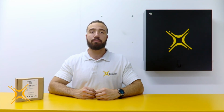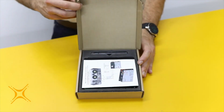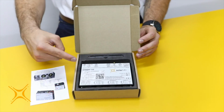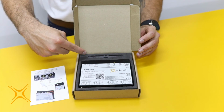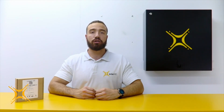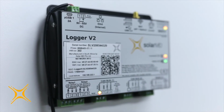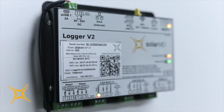Step 1. Unpackaging. Once unpackaged, you should have the following: a quick installation guide for the most common inverters, the logger itself, and a Wi-Fi antenna. The package does not include a power supply, since the logger is specifically designed to work with 24 to 48 volt DC battery systems and can be directly supplied from the battery busbar. The front of the logger provides the following information: the serial number, Wi-Fi SSID, Wi-Fi password, and local IP.